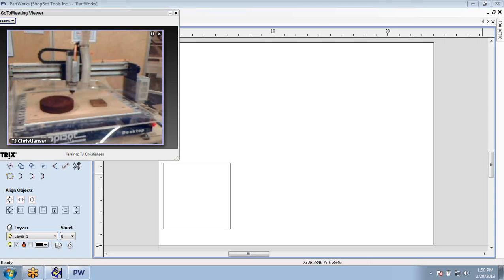I cut some guide notches and a grid in the spoilboard, then use them as reference. Yeah, like Justin said, he does that. We've got a guy here who cuts a fence in his, so he has a 1/2-inch fence all the way around, so he can just nudge his part up to it. And then when he draws, he always draws in a 1/2 of an inch. So there's lots of different ways. There's so many different ways.